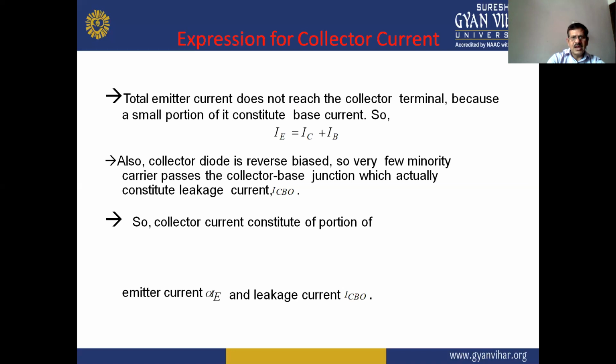Also, the collector diode is reverse biased, so very few minority carriers pass through the collector base junction, which constitutes leakage current, ICBO.